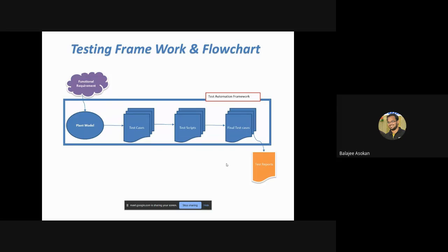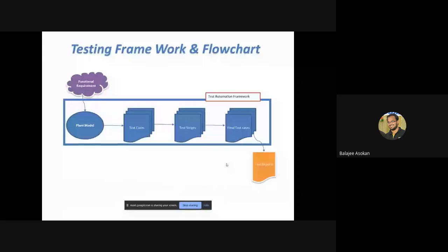So whatever test cases we have written, we have also covered the functionality part, which is dealing with addition of two numbers, and also the structural part, whether the signals are taken care of. Now, since an error is observed here, he needs to go back and tell his OEM that when both inputs are uint8, you cannot have uint8 as output. Better to have uint16 as output, or a data type where the operational range is more. In that case, when they give 255 plus 255, it will give 510 as output. So this is how your test cases are written.